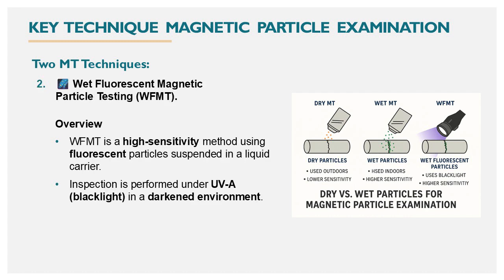Next is technique number 2 called wet fluorescent magnetic particle testing or WFMT. Wet fluorescent magnetic particle testing is a high-sensitivity method using fluorescent particles suspended in a liquid carrier. Inspection is performed under UV, blacklight, in a darkened environment.